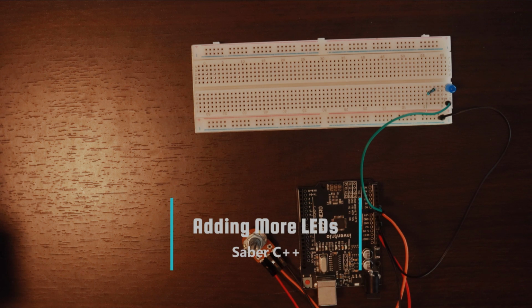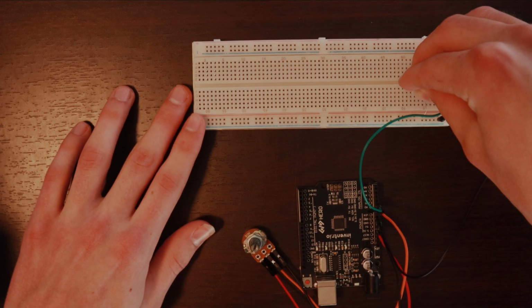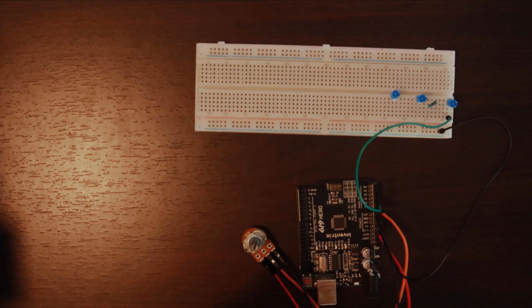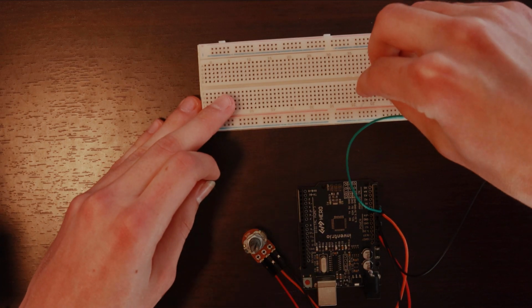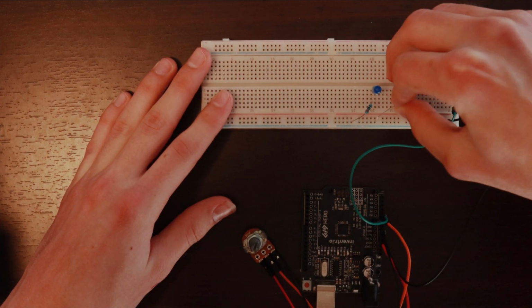Let's make our circuit a little more complex by adding a few more LEDs and then using the potentiometer to switch between them. I'm going to add 3 more LEDs, making sure to keep the positive side of each LED to the right, so that I can easily tell when I'm making my connections. Then, I'll connect resistors from the negative side of each LED to the blue negative line on the breadboard.